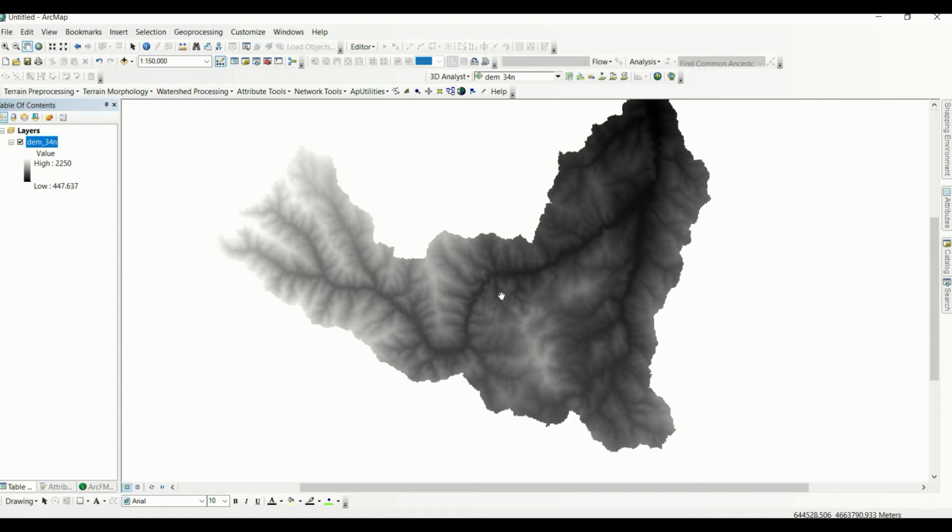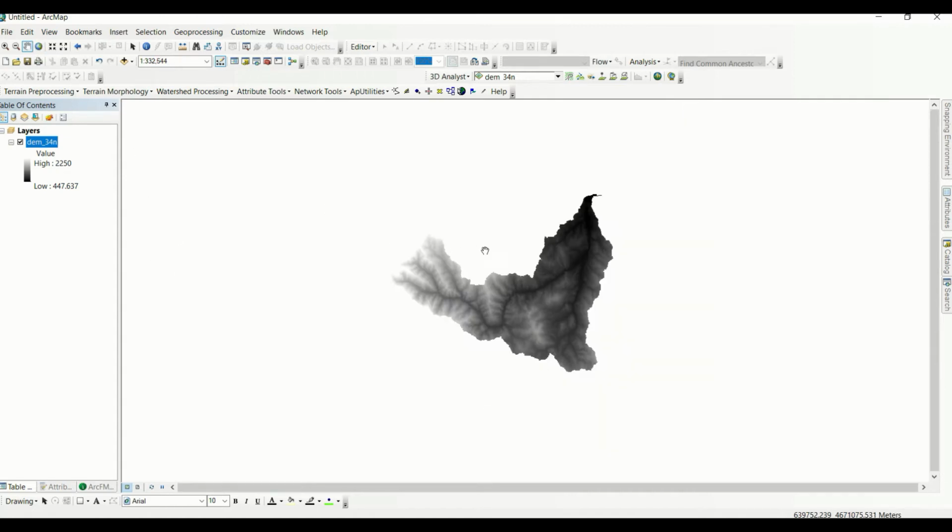In general, it is 2D data. To view it in 3D, we need to use software like ArcScene or ArcGlobe. However, within ArcMap, we can simulate this 2D data in a 3D view. For that, we can calculate a hillshade and set the transparency of this dataset, and it will be shown as 3D. Let's check.